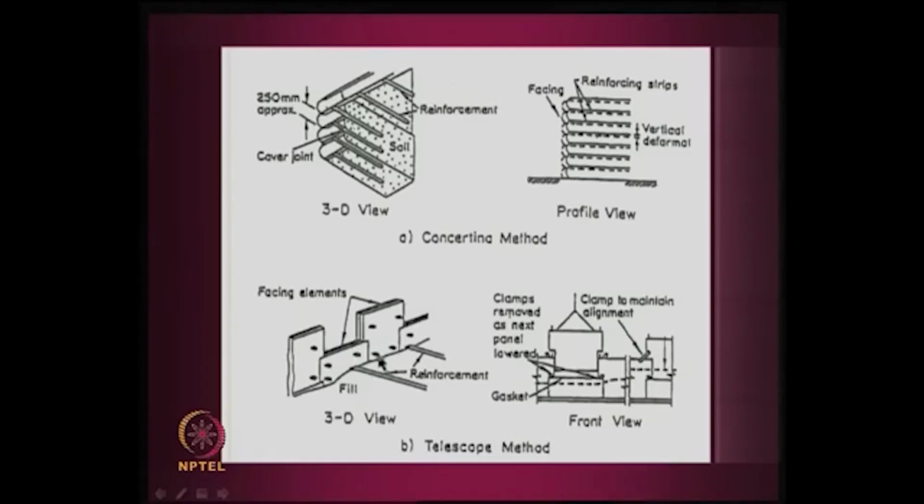Then from where it cuts, you have to calculate the frictional area of the geotextile per meter length again. If you are able to calculate the friction force along the geotextile, and it is more than twice this, it is all right. That is how the simple design is done, and the way it is practiced in the field is that you have concrete panel facings and you have some sort of this thing here, like so.